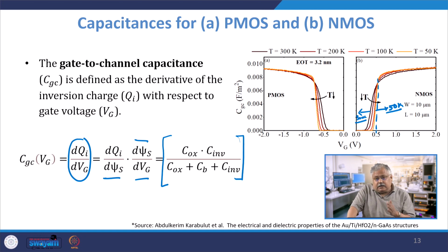However, as you cross the threshold voltage, the rate of increase obviously reduces, and the reason for the reduction is that by this time the number of charge carriers has increased so much that even with an increase in the value of VGS, the incremental addition in the inversion charge is very small. I have already given you an example. Say you are adding 10 to 10, so that's a 100% increase, whereas if you are adding 10 to 100, it's almost a 10% increase.